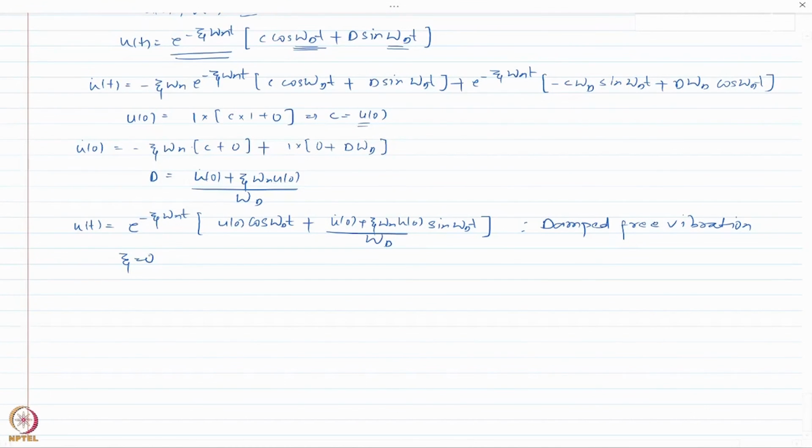So I can just verify that from here. But for an undamped free vibration, there is no damping, so the amplitude is constant, it is not changing. However, I have an exponentially decreasing term which would be non-zero if the value of damping is non-zero. So the amplitude of damped free vibration is decreasing with time.